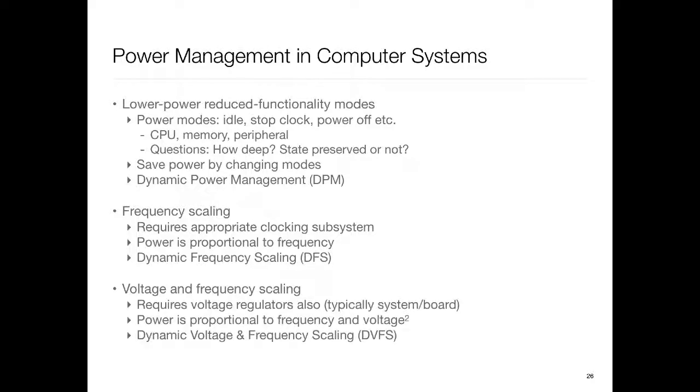So that leads to the third technique, which is voltage and frequency scaling, where we need some support so that the voltage regulators providing the voltage are software controllable.